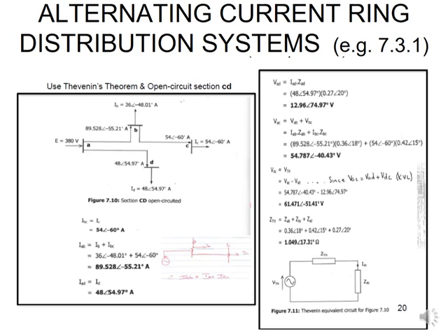So the first voltage we look at is your VAD, which is at the bottom here. That VAD was simply going to be the IAD that we've worked out multiplied by the ZAD that they give you in the system. And that gives you that voltage that you have there. Then you want to know what the VAC voltage is. VAC, you can see, is going to be a combination of VAB and VBC. You already have IAB and you've already got IBC, so you can substitute and work out what VAC is.